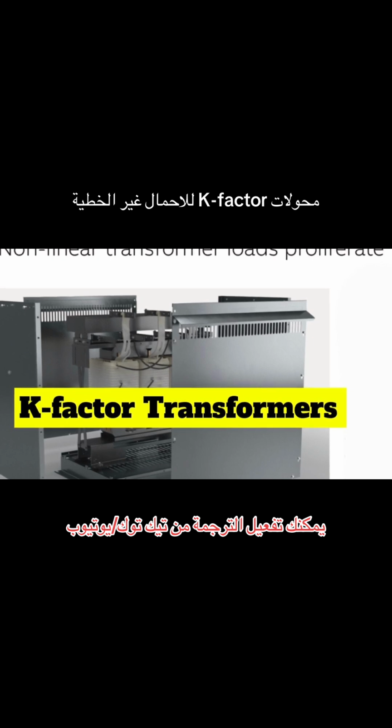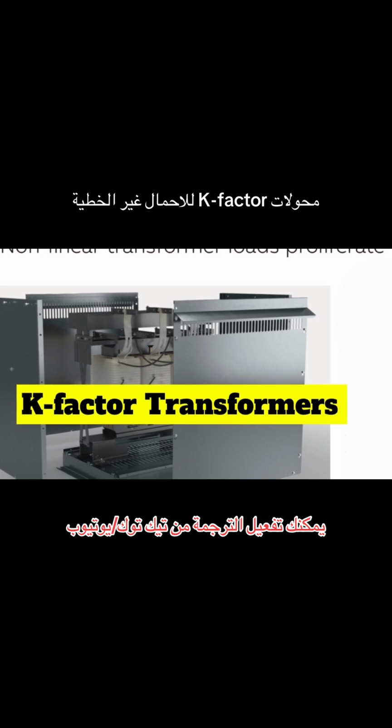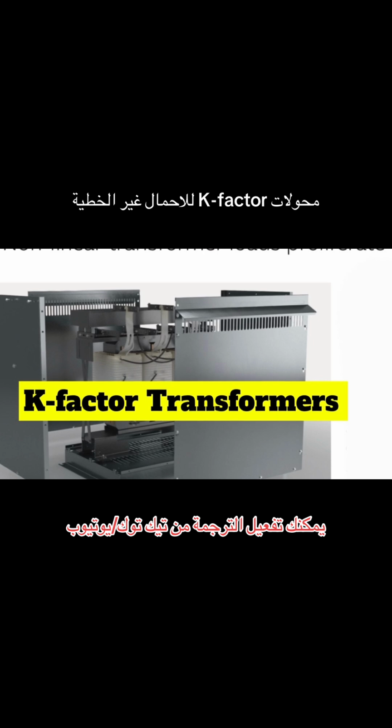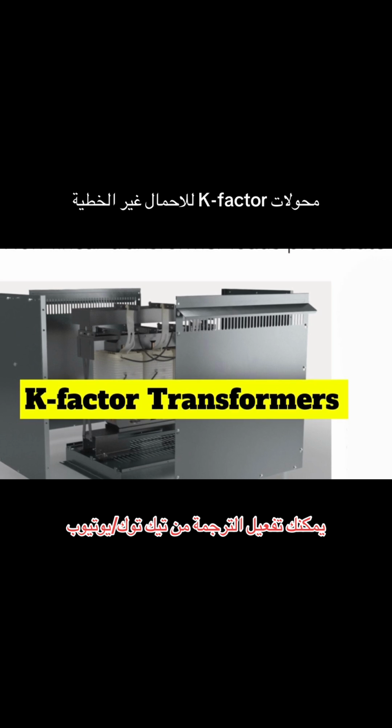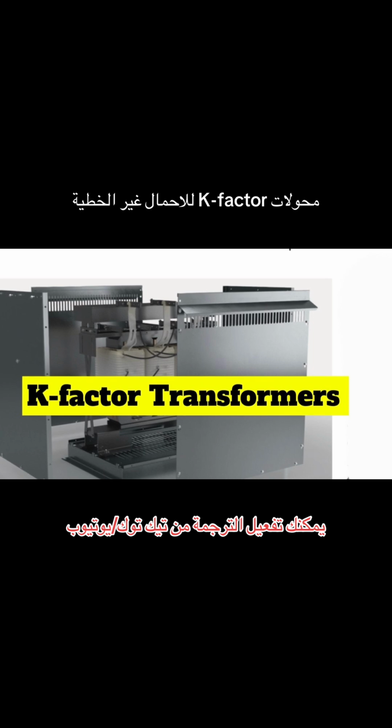And how do I know if a transformer has a specific K factor? Is it like a label? Yep. You got it. If a transformer is K-rated, that K-factor value will be clearly marked on its nameplate right there with all the other important information. Okay, that makes sense. Now, here's another important point. The K-factor isn't just some arbitrary number. It directly tells you how much bigger a standard non-K-rated transformer would need to be to handle the same amount of nonlinear load without overheating. So it's a measure of how much extra capacity is built in to handle those harmonics. Exactly. A higher K factor means you don't need to oversize the transformer as much, which can save you space and money. That's practical. Very much so.